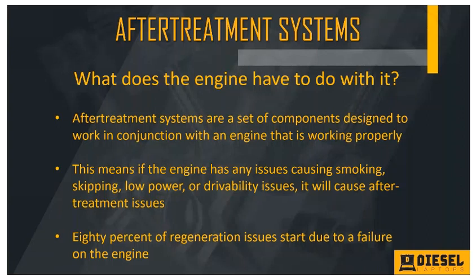So what may start as a very small issue up top, an EGR cooler that's leaking just a little bit of coolant, starts trickling downstream and turns into an issue where your DOC is completely face plugged and it can't regenerate. It's not efficient, so your temps never get hot enough. And then your DPF's full of soot, it's full of ash, and it can't regenerate. And then the next thing you know, your engine can't get exhaust out.